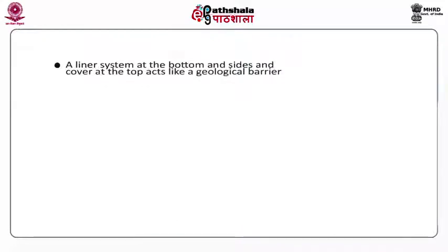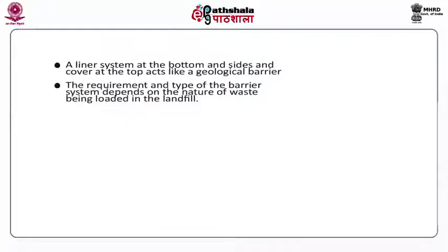Now, a liner system is provided at the bottom and the sides and on the cover, which acts like a geological barrier. The requirement and type of the barrier system will depend upon the nature of waste that is being loaded. The liner materials, both natural as well as synthetic, are used as barriers.